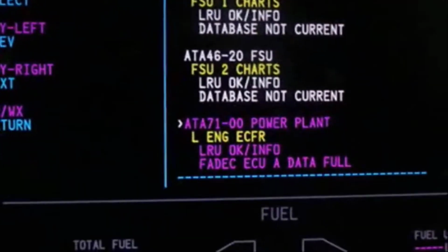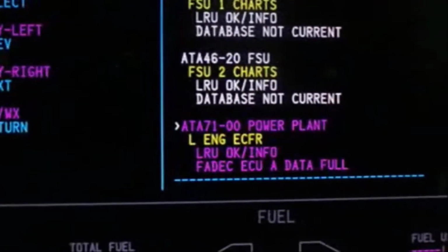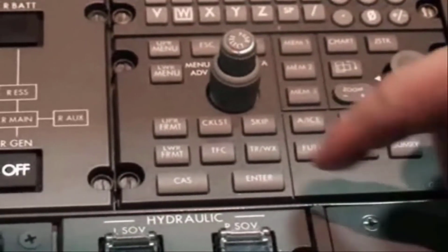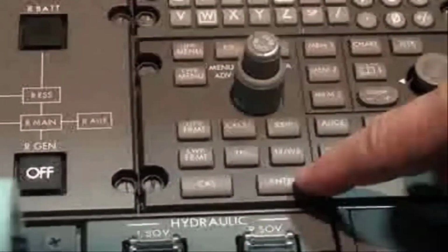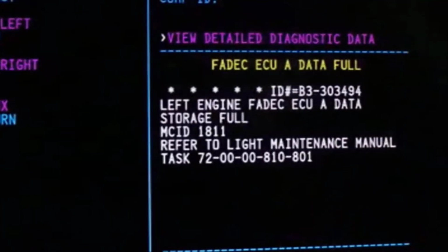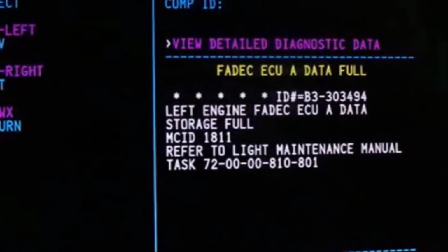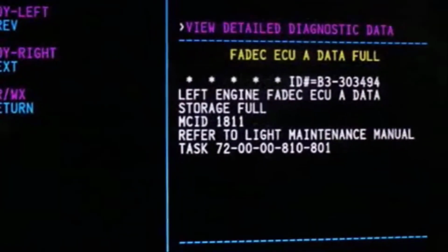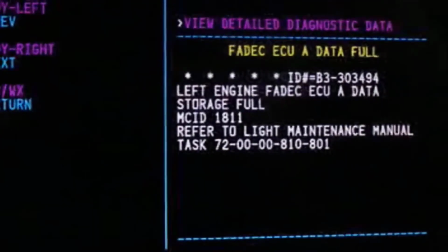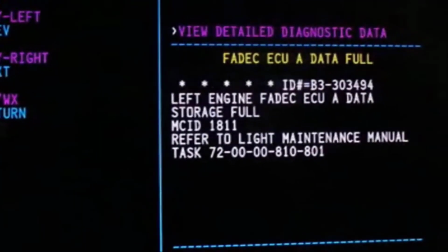We will highlight and select a service message, and by pressing the Enter push button, we'll open the Advanced Diagnostics page. The information displayed here includes LRU, LRU status, ATA number and name, as well as detailed help for troubleshooting, similar to the Current Faults Advanced Diagnostics.